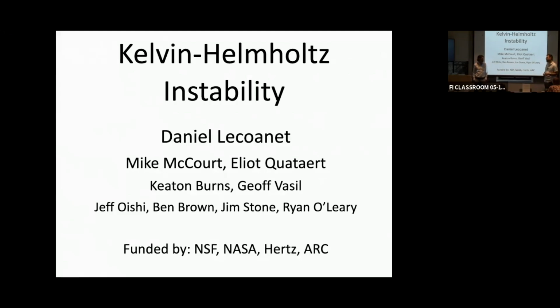This often happens when you solve an elliptic or parabolic type equation. So a solution to the heat equation or something like that will have many smooth derivatives if the forcing is smooth. And this is also a property we tend to see even for turbulent flows at low Mach number. So in the viscous range, when you have dissipation by viscosity, you'll tend to have highly differentiable solutions. If we do a simulation, say, of turbulence, and we have enough resolution to resolve into the viscous dissipation range, then the solution is highly differentiable. And as we add more modes, then the numerical truncation error we get will fall off exponentially.